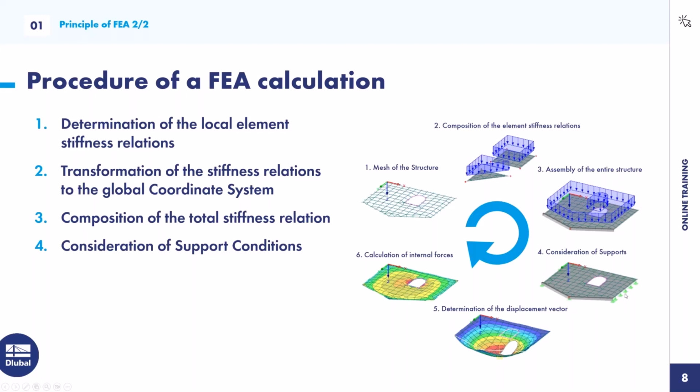So we can just strike out the corresponding entry in the stiffness matrix and the displacement vector. After doing all of this, we can solve the equation for the U vector, the displacement vector, and find our displacements. After having the displacements, we have everything known about the system.